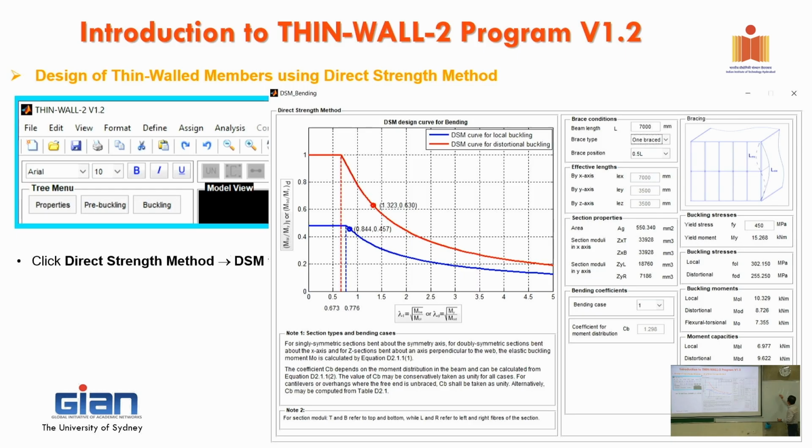So when you've got a channel section and you put the shear load up here, the shear flow will go like this one. And this is parabolic. So that is how the shear flow will run along this. That is the stress distribution.